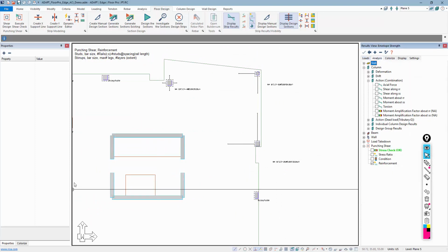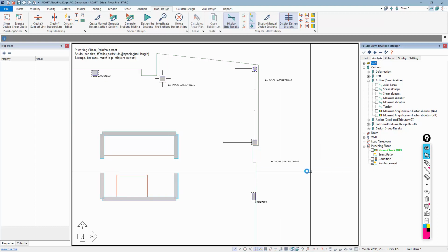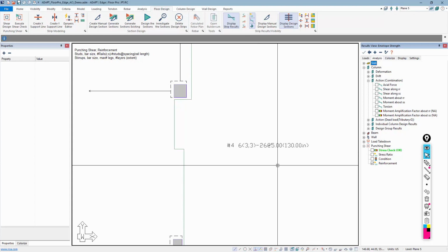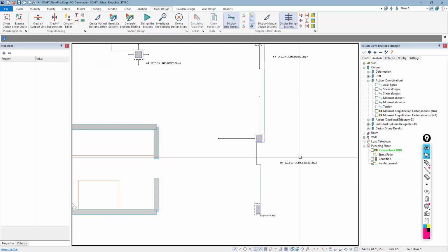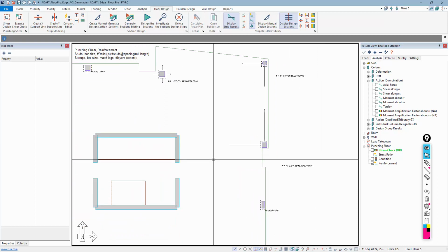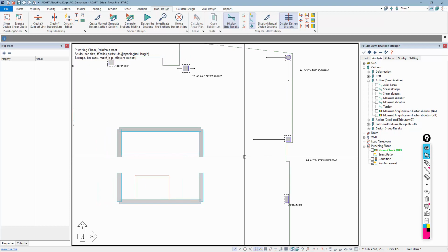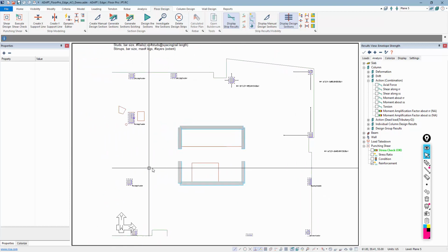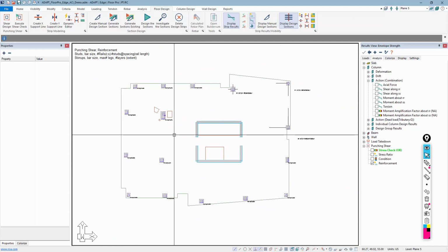So there is a condition where the spacing of a calculated versus uniform is identical, and this looks like one of those conditions where these are the same, regardless of what you select there, even here as well. But that's something that a user may want to check to see what the difference is and to what extent you have more studs if given a uniform condition based on the description of how that's being calculated that I provided earlier. So this is some of the graphical output that you can achieve through use of this result browser in the program.